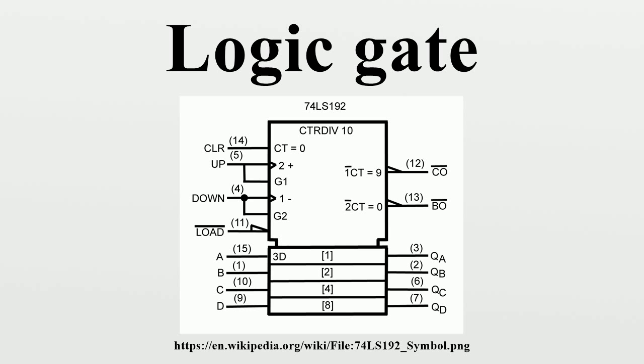Consider the simplified case where a two-input NAND gate is used to drive a motor when either of its inputs are brought low by a switch. The signaled state occurs when either one or the other switch is on. Unlike a regular NAND symbol, which suggests AND logic, the De Morgan version, a two-negative input OR gate, correctly shows that OR is of interest.